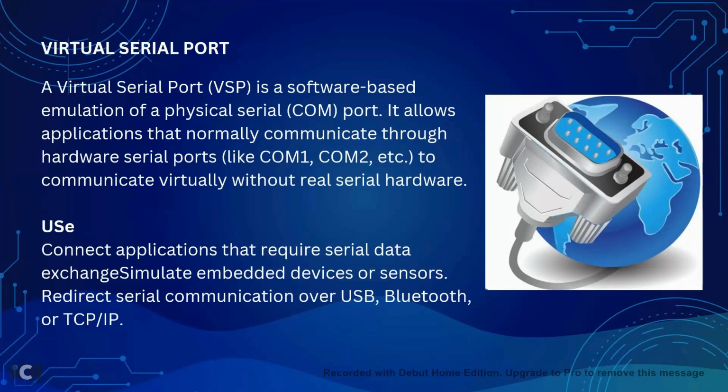Virtual serial port. This port is used to connect our serial tank to the PICSimlab. For this, we require a virtual serial port. A virtual serial port is a software-based emulation of a physical serial COM port. It allows applications that normally communicate through hardware serial ports like COM1, COM2, etc. to communicate virtually without real serial hardware.